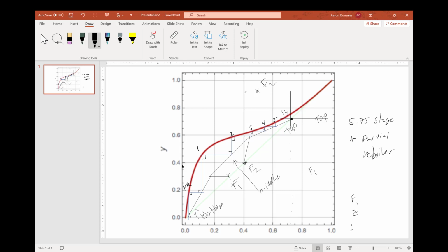So what was that all to say? All this work, all the rigorous mathematics and graphing, was all to say that if you had an incoming feed 1 and incoming feed 2 of these compositions and these phases coming into a distillation column at these settings, and you wanted a distillate of purity as high as 72%, and you wanted a residue as low in ethanol as 2%, then you would need this. So the whole thing was to design a distillation column. The column needs to have this many stages, and you can't have 5.7, so it would be 6 stages, plus a reboiler.